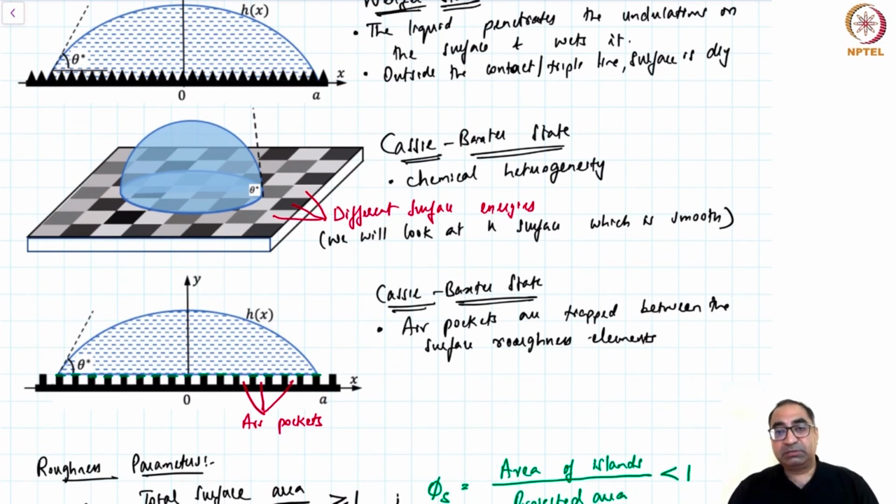One way you can promote a different kind of wetting is, let's say you take a Cassie-Baxter state with tiny air pockets, you could continuously shake the droplet and effectively change the wetting nature. We will look at the Cassie-Baxter model where we have tiny air pockets between the roughness elements, and then we will look at some simple transition criteria, and it's not exhaustive by any means.